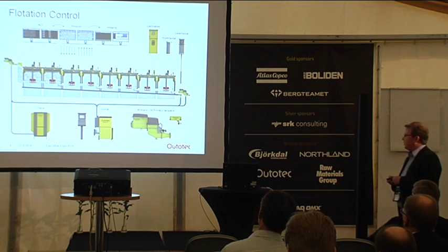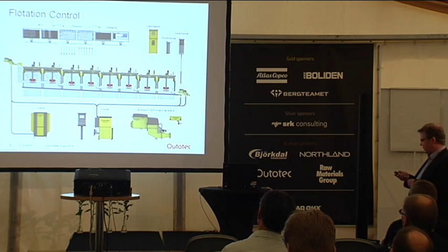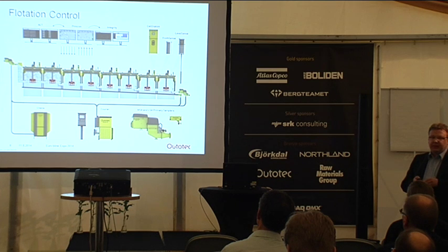Flotation control needs a little bit more instrumentation and analyzers there. Samplers are very important around this process for process control, to take samples around the full mass balance area or sub-mass balance areas in order to determine the grades and recoveries online.